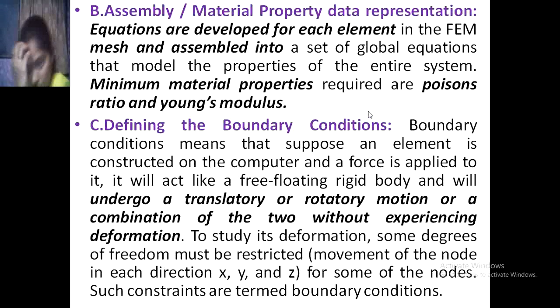So defining the boundary conditions. Boundary conditions means that suppose an element is constructed on the computer and if force is applied to it, it will act like a free floating rigid body and will undergo a translatory or rotary motion or a combination of the two without experiencing deformation.